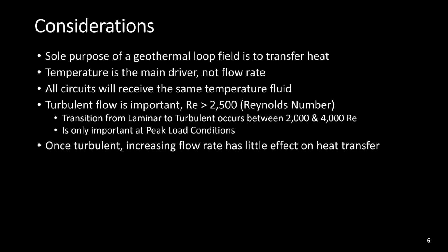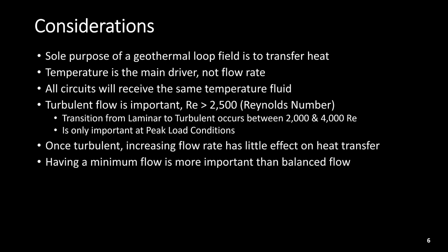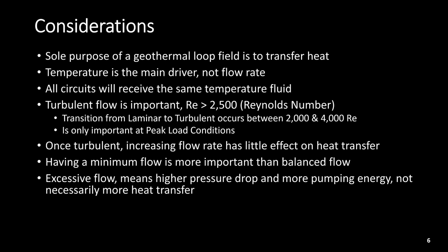Once you're turbulent, increasing flow rate has little effect on heat transfer. Having a minimum flow to create turbulence is more important than balanced flow. Excessive flow means higher pressure drop and more pumping energy, not necessarily more heat transfer.